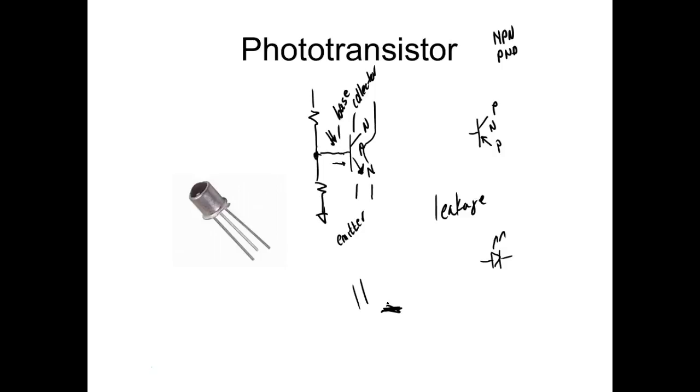I got off track. So the thing's transmitting light. So we got a robot. I didn't bring one over. I can get that. That's an avoidance robot. What it's doing is pulsing the light out of an LED, and then it looks for reflection to come back off a surface. Depending on which angle it comes off, that would tell the controller which way to turn the robot. I'll bring one of those over here too.